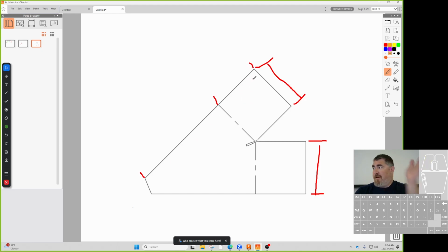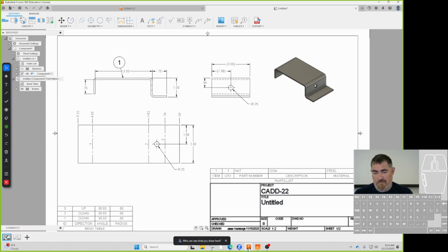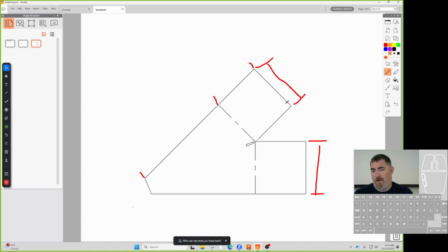But usually ordinates we can only do at right angles. So here I might just do that dimension and then that dimension. Well, I'm saying doing ordinate from the opposite end, as opposed to the narrower end. Oh, from starting here, go this way? Yeah, into the line. So you can start it there, at 0, and boom, boom, and just say typical, because you can't reestablish it here because it'd want to be horizontal and vertical, not at this angle. Or you can just do the regular end-to-end dimensions there.